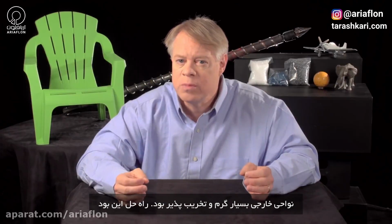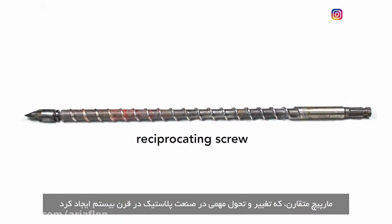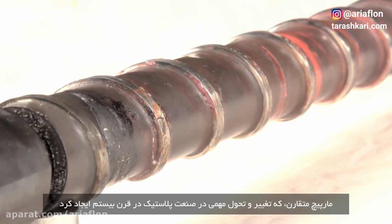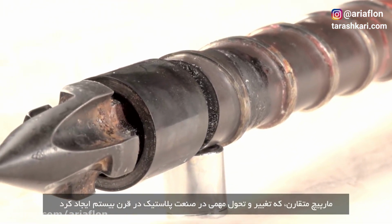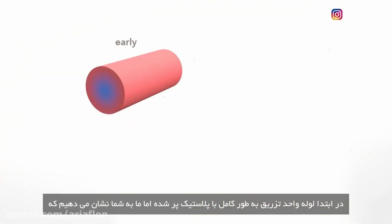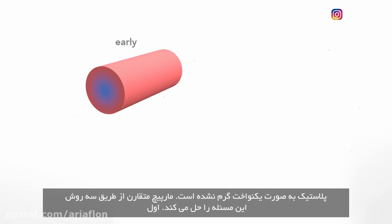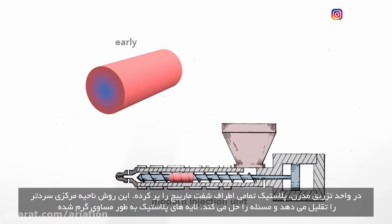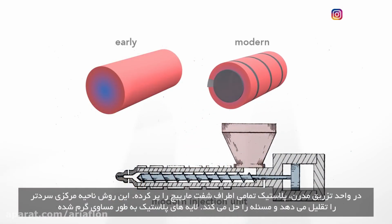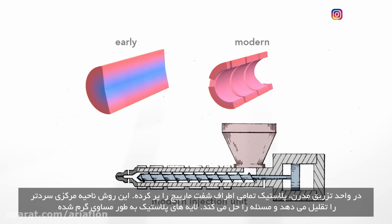The solution was this: the reciprocating screw, often regarded as the most important contribution that revolutionized the plastics industry in the 20th century. In the earlier plunger-style machines, plastic filled completely the cylindrical barrel. But as I showed you, the plastic was not at a uniform temperature. The reciprocating screw overcomes this in three ways. First, in modern units, the plastic fills only the space around the shaft of the screw. This eliminates the cooler central region, leaving a thinner, evenly heated layer of plastic.